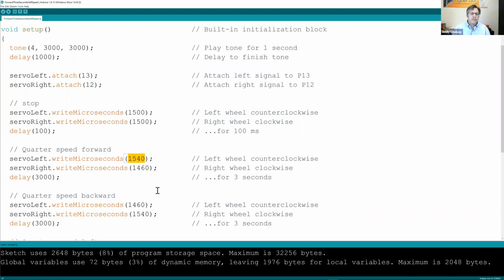And so it's true that you could somewhat adjust it. You could probably adjust your potentiometer. Like if you decided to set these 1500s to say 1520, that would probably work. But things are going to get a little weird if you go very far above or below 1500 for that center position, because it'll affect the speed of the servo in a particular direction and how it responds.